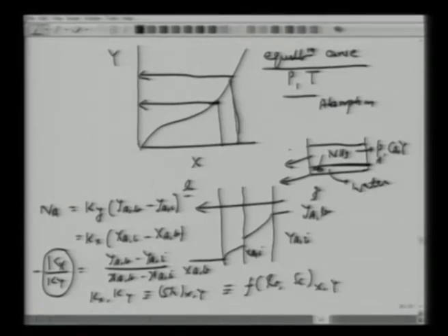Okay, so now let's plot these points again on the xy plot. We have the equilibrium curve between y and x, and this is our bulk concentrations given in gas phase and water phase.